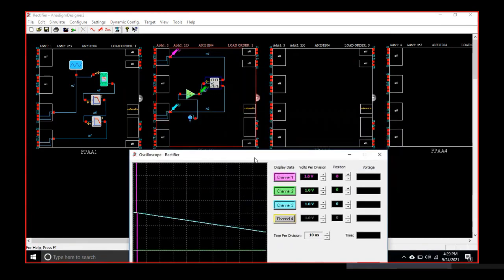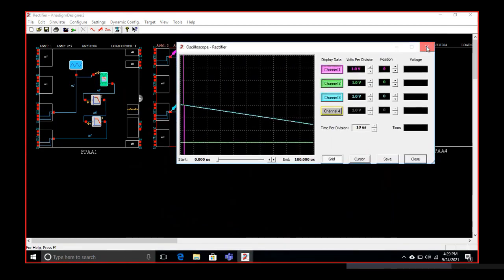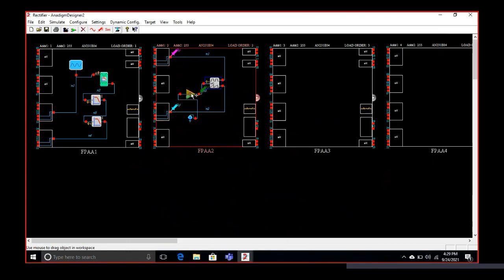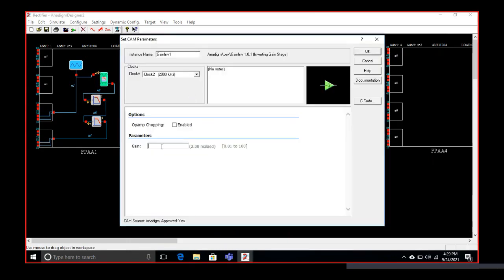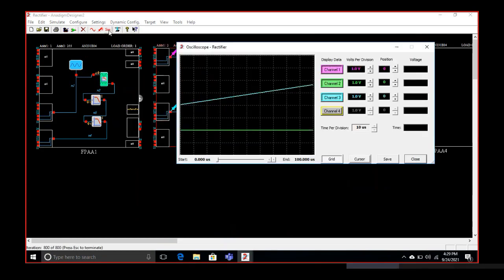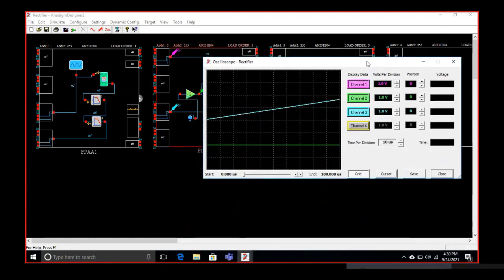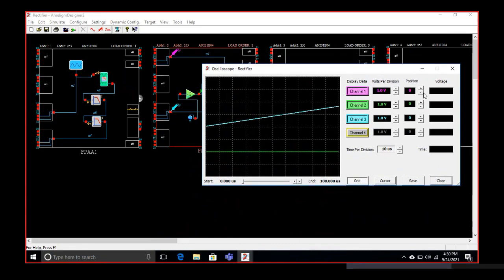You do one thing. Reduce the gain. Reduce the gain to 1. Gain of inverter or gain of inverting amplifier. Again, it is the same way, but signal 10 microsecond only. Now you simulate the circuit which I have shared.